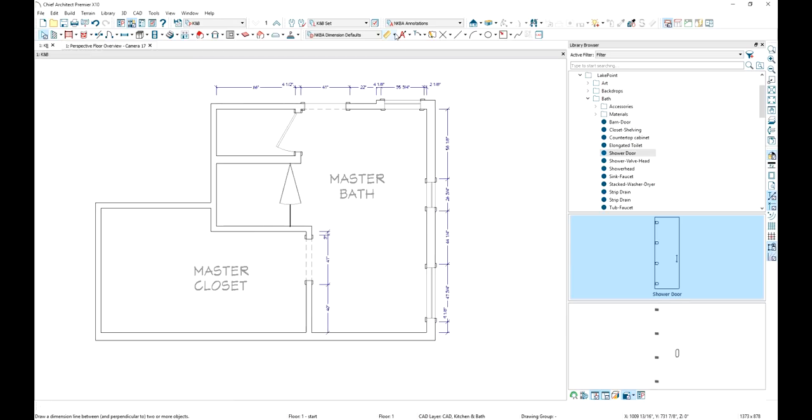If you want to use the interior dimension tool, let's go ahead and use the interior dimension tool, and we'll draw a couple of dimension lines through here. Go ahead and pull this out. Now it's picking this extra dimension up because we have a wall type change. We'll just pull that extra dimension off. Again, let's just use our interior dimension tool and draw a few dimensions across here.